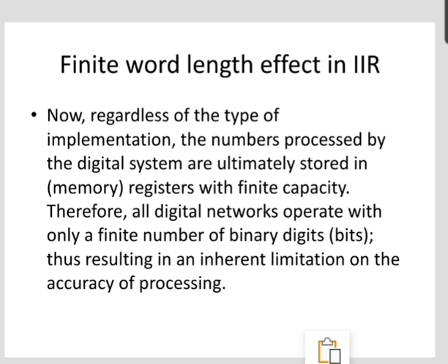Overflow in addition of two or more binary numbers occurs when the sum exceeds the word size available in the digital implementation of the system. Limit cycle: since the quantization is inherent in finite precision arithmetic operation, the system is nonlinear. In recursive systems, these nonlinearities often cause a periodic oscillation to occur in the output even when the input sequence is 0 or some non-zero constant value.